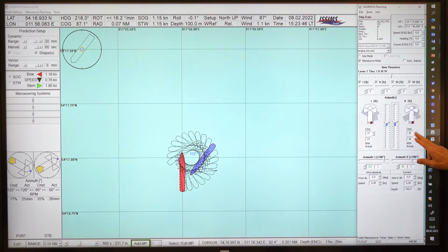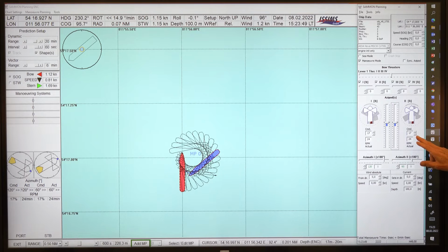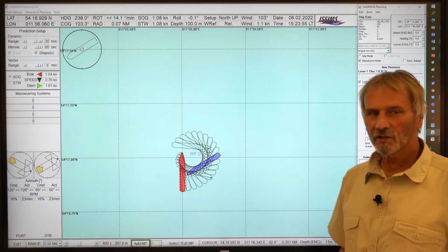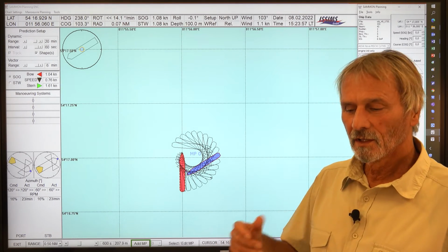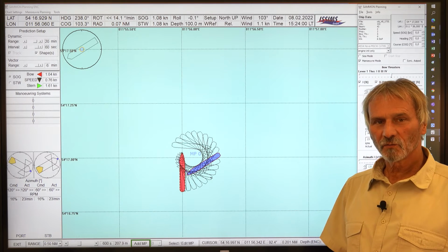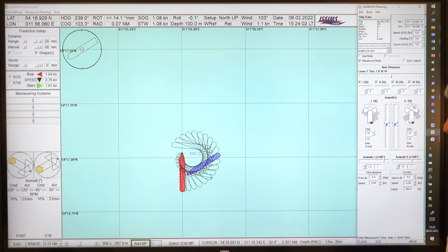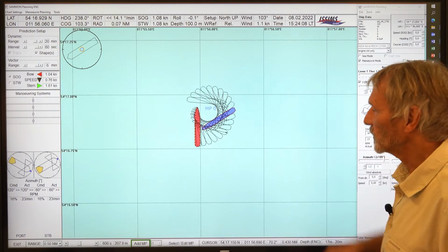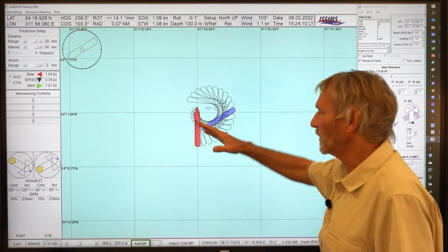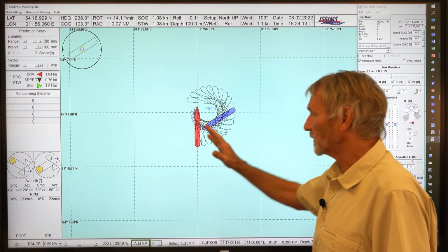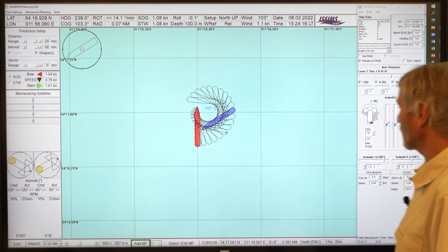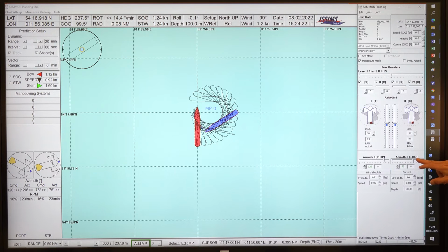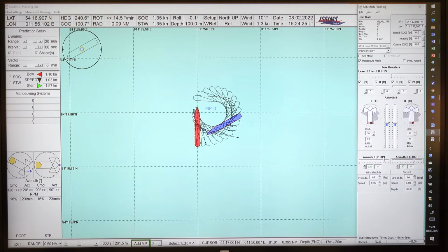So we have to adjust it to maybe 17% or maybe 16%. So then the picture is the same as we had for the one single pod version with 90 degree resulting thrust angle. Okay, so if you want to use the ship then in a situation that the thrust will be needed, the thrust vector, resulting thrust in this direction, then we could not easily go with this one to high angles. So maybe 90 degrees might be the maximum.